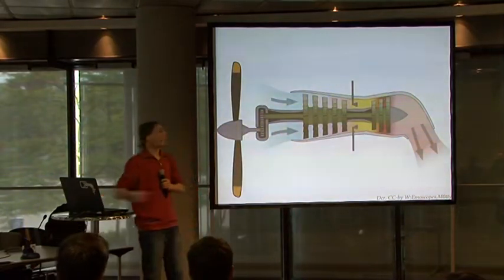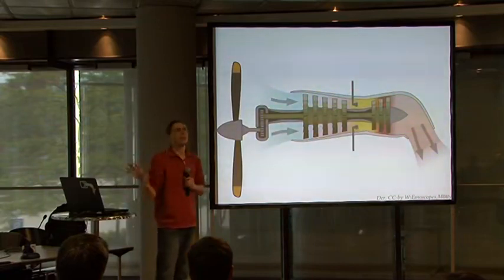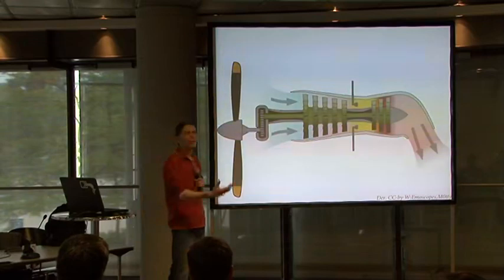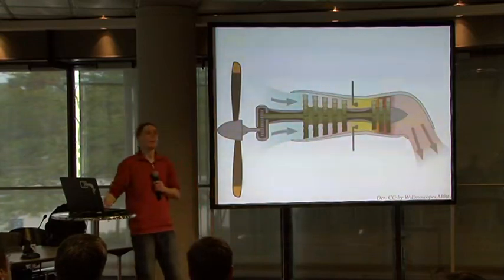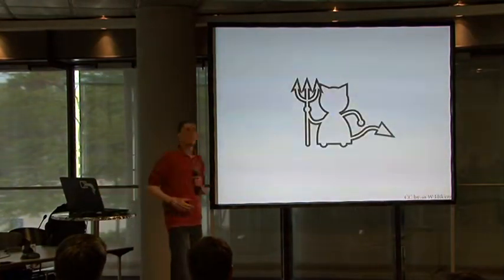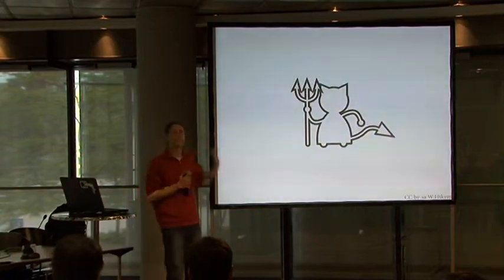So that reduces the loss a little bit, but it turns out there's no way around a large amount of loss. Typically, the best you could do with a frictionless, perfectly designed, perfectly slow, perfectly large engine, for a given temperature, would be 70%. And by the time you make this compact and reactive and economical, cheap enough to be built, then it's down to 20, 30%. And in comes something that's extraordinary in physics, in thermodynamics, from my point of view, which is Maxwell's demon.